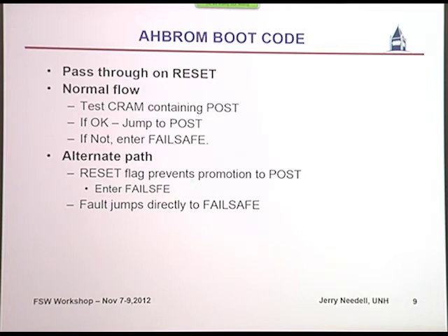Also, if for some reason we don't want it to promote up the chain, either because we're doing a test or some diagnostic, the FPGA interprets the reset command and can pass flags into the flight software so that the AHBROM code can detect a flag that says don't promote to POST, stay in the failsafe, stay within the FPGA, and wait for further commands. Otherwise, if certain faults occur in the higher level system running in the RTEMS image, we'll jump directly into the failsafe and wait.